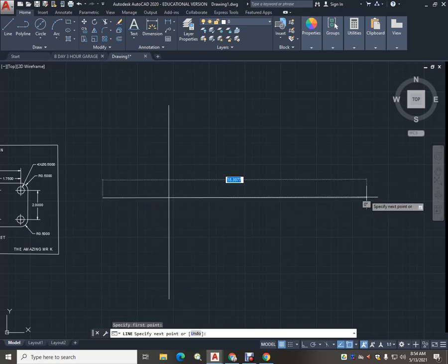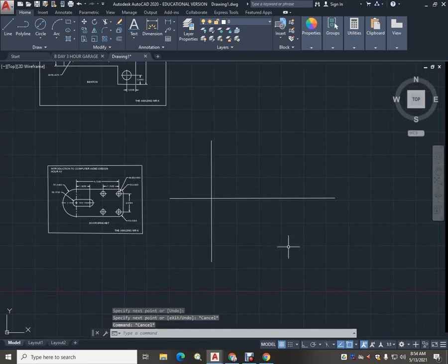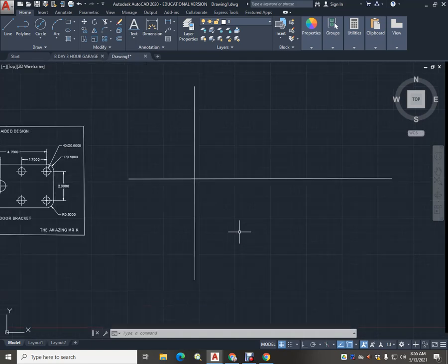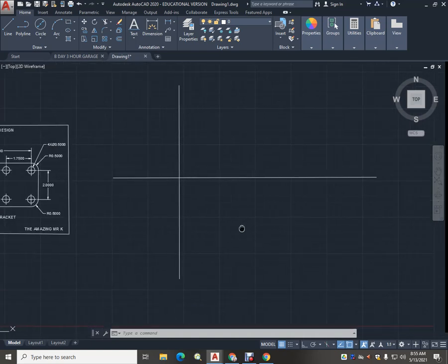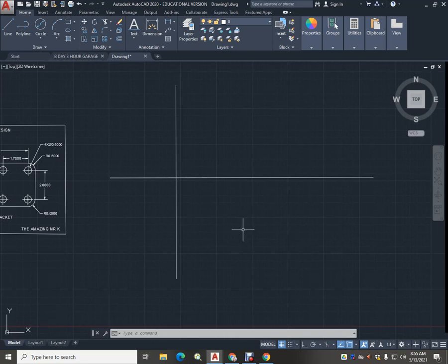Anytime that we have parts that are mostly circular, I always like to start with a big old X on the page or a T, and that way we can start on these construction lines that would allow us to get things going. So right off the bat, we have circle commands. Remember that there's two ways that we can put circles on there.